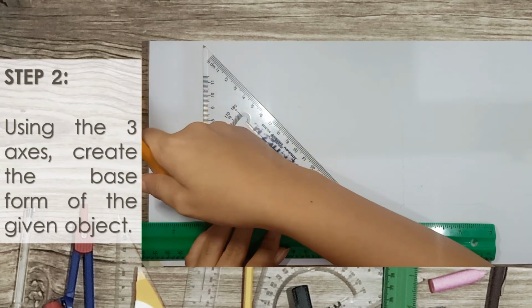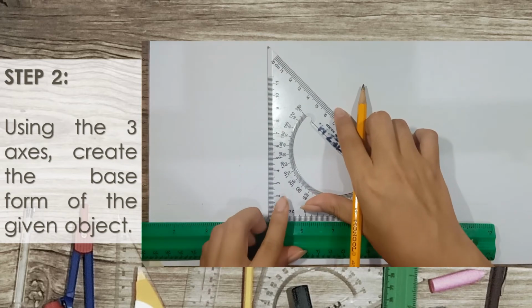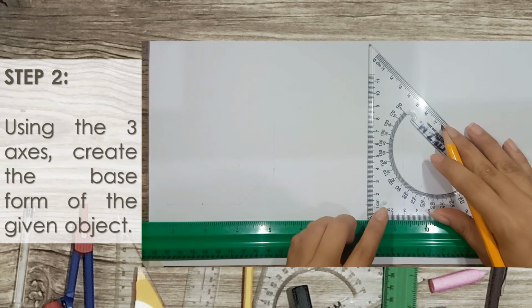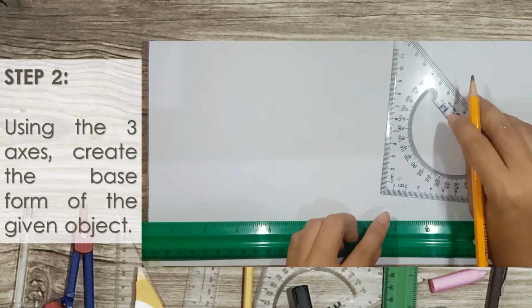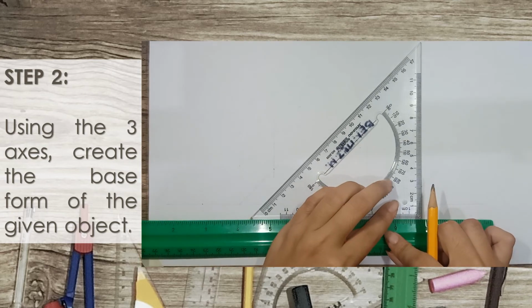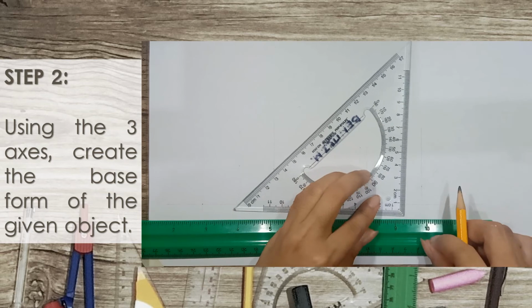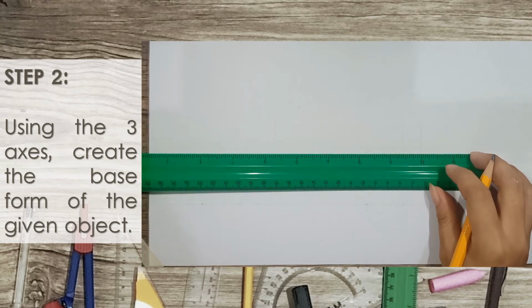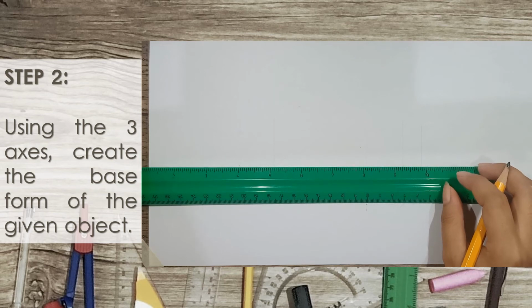We will be projecting all the vertical lines from both the cabinet and cavalier. So there, we have projected the vertical edges of the drawing. The next would be projecting all the horizontal edges.